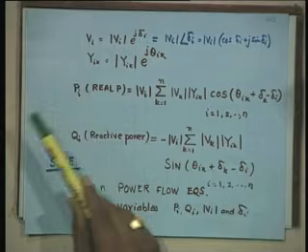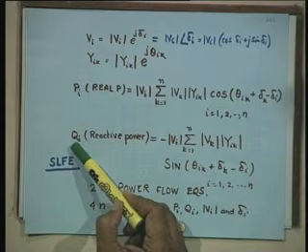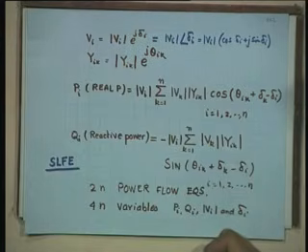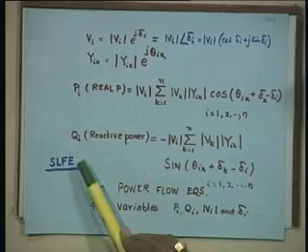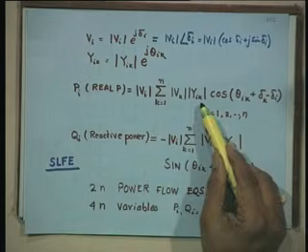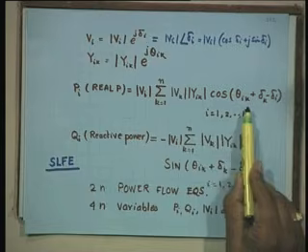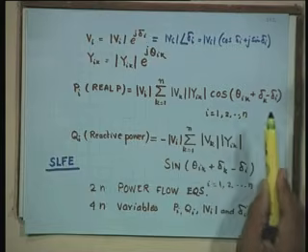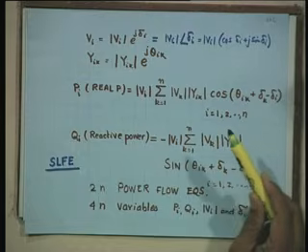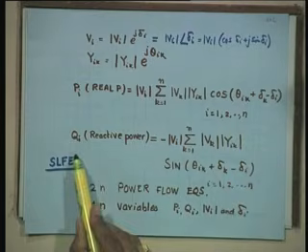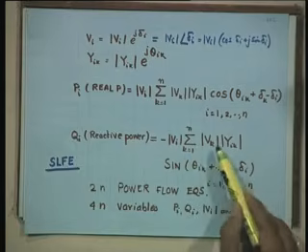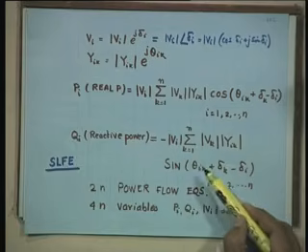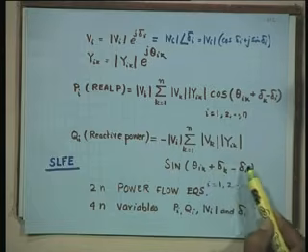Expanding those earlier two equations for P_i and Q_i, which we just now saw, and substituting this voltage and admittance, we get P_i equals |V_i| sigma k equals 1 to n |V_k| |y_ik| cosine of (theta_ik plus delta_k minus delta_i), i varying from 1 to n. And similarly, for reactive power we get Q_i equals minus |V_i| sigma k equals 1 to n |V_k| |y_ik| sine of (theta_ik plus delta_k minus delta_i).